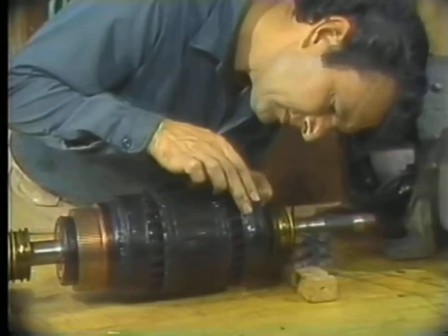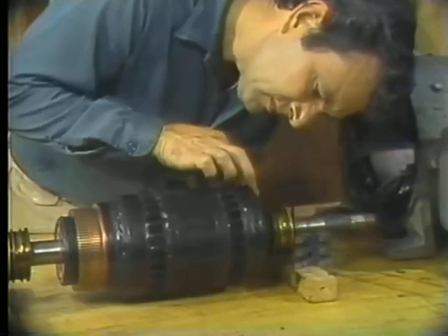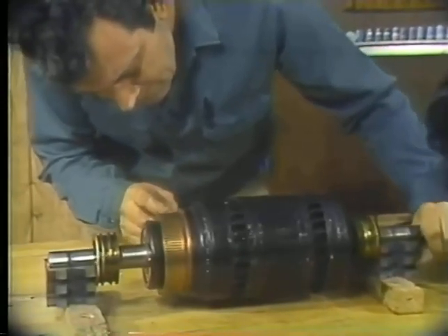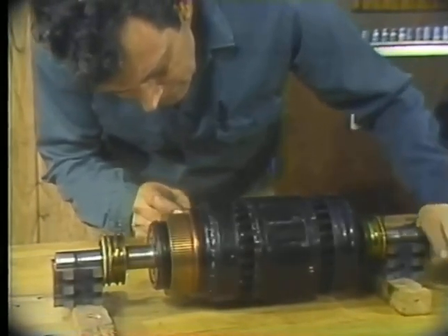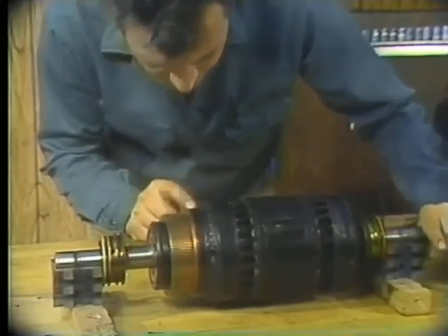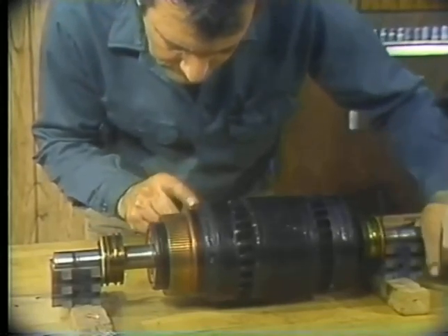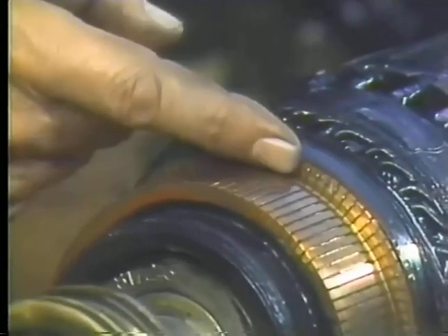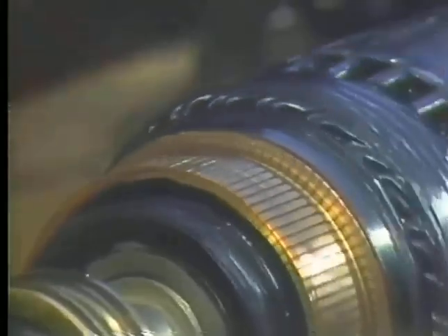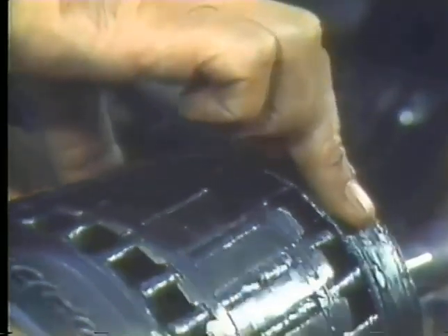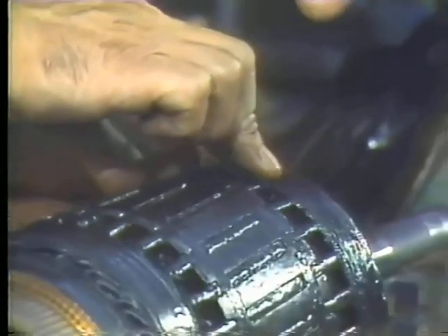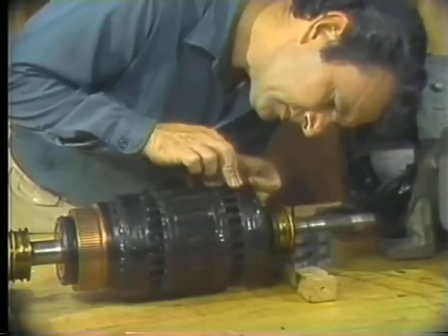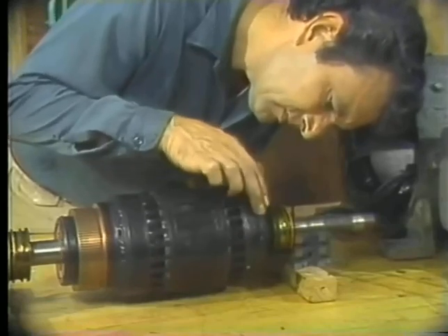Inspect the armature windings. Look closely at the area where the windings connect to the risers. See if there's any evidence of solder being thrown out of the risers. Thrown solder's usually an indication that the commutator's overheating. It could mean that the motor's running overloaded or that you've got armature winding damage. We'll go over how to check for damage to the windings in just a moment. Check the armature banding to be sure it's tight and intact. Check the back of the coils for damage. Pay particular attention to the condition of the insulation.